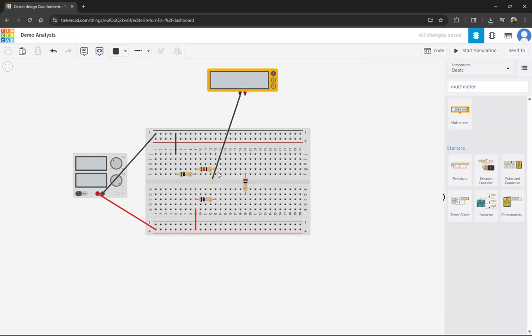Remember, we're connected vertically. We don't want to go off the end of the resistor because there's no electrical connection between here and here. We want to go vertically, deselect, switch back to red, and drop it in here. Now I'm not connected anymore because I'm so far apart. I need to go from this column to throw a reconnection in there. And in the case of a physical breadboard in a laboratory setting, these are literal physical wires. These would be jumper wires, right? That we sort of plug in. And if I start my simulation,